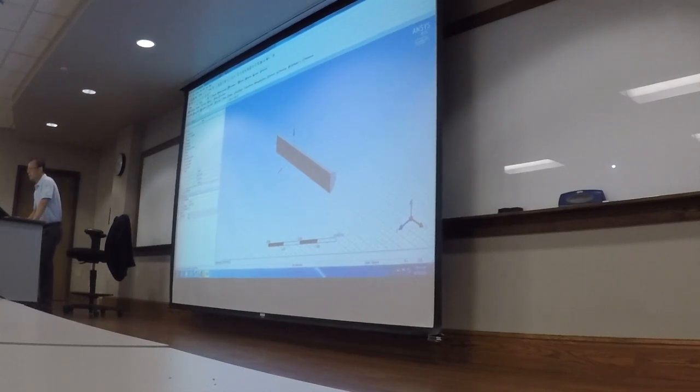Now let's extrude that 4 inches. So come here, extrude. All right. And geometry, extrude what geometry, just click on apply. And this software is smart enough to recognize we're going to extrude sketch 2. All right, not 12 inches this time, let's only do 4. Generate.